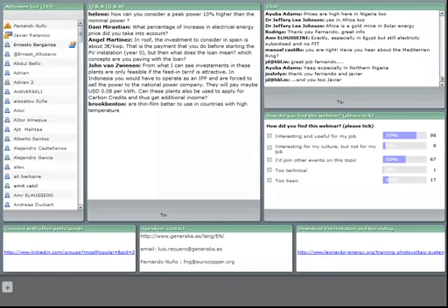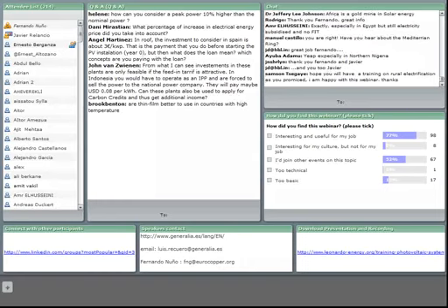If we are using thin film modules, we only have to consider 2% losses for every 10 degrees. So it will be better getting thin film modules in countries with high temperature, yes.